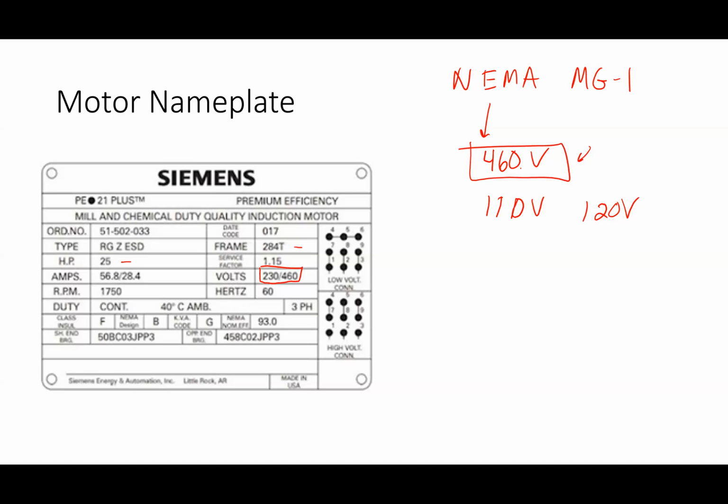All right. Now it also tells me here that his rated RPM is 1750 RPM. How many poles do you think this thing has? 4. With 4 poles, what would be his full speed? 1800 RPM. That would be his full speed. When he's operating at rated speed, he's at 1750. Only 50 RPM different. He's slipping a little bit, but he's not slipping much, at rated operation.